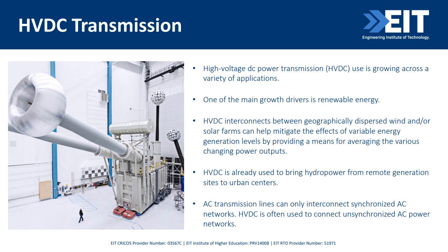with renewable energy, some countries are really advantaged, like they have the best solar irradiance or a good wind profile. So there are a lot of projects where the generation is happening in one country, and then the power is required to be transmitted to another country. So that's a long distance transmission. That's where HVDC has an advantage over the AC transmission, which we normally use.